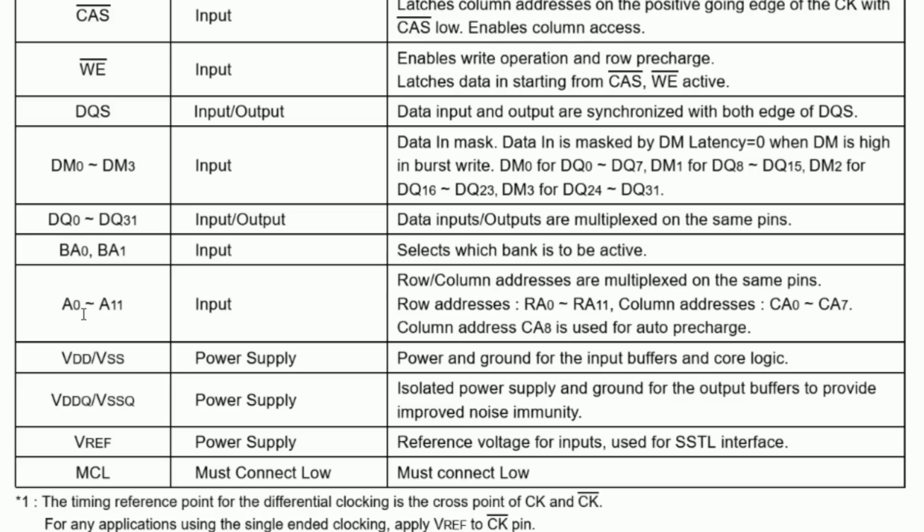But the trick is that there are rows and columns. So a word of data is addressed by a column address plus a row address. So effectively you get 12 bits in the row address and an extra 8 bits in the column. And that was the first clue that I got. So why is the column address limited to only these bits? We have more bits, so can we just add another bit and then get double the memory?